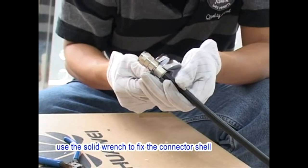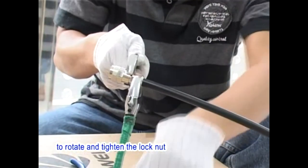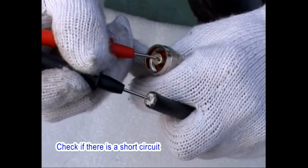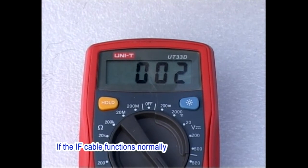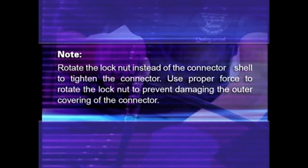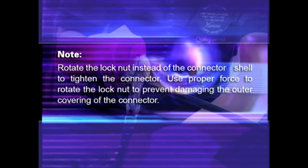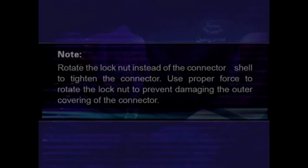Specifically, use the solid wrench to fix the connector shell and use the adjustable wrench to rotate and tighten the lock nut. Check if there is a short circuit or an open circuit in the IF cable. If the IF cable functions normally, it indicates that the making of the IF cable connector is successful. Note: rotate the lock nut instead of the connector shell to tighten the connector. Use proper force to rotate the lock nut to prevent damaging the outer covering of the connector.